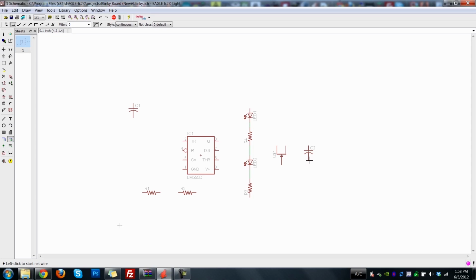You can either just connect all the grounds in the circuit to each other, or you can add a special component that defines a ground and adds anything attached to that net or that signal layer as a ground. So let's go ahead and do that.